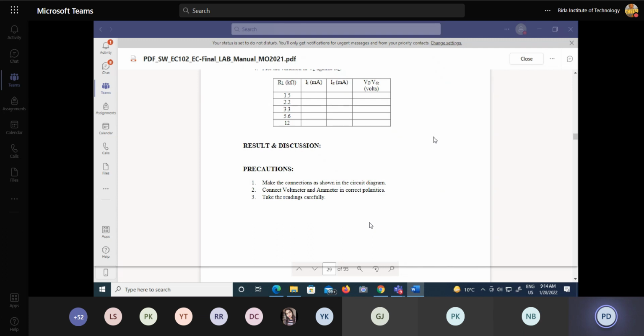Okay, so basically a Zener diode is very heavily doped, means the doping concentration is more. As the doping concentration is more in a Zener diode, obviously the concentration of charge carriers is also more, and the depletion layer region is very thin in the case of a Zener diode. So this is the primary difference, due to which we get the difference in the characteristics of your Zener diode and a normal PN junction diode.